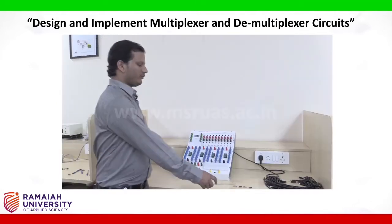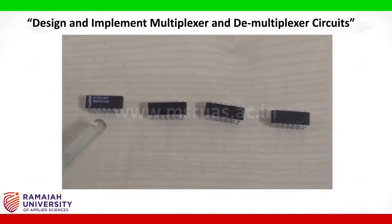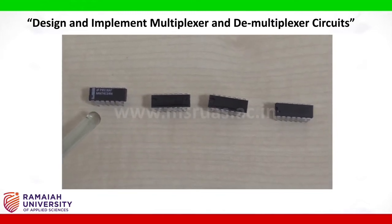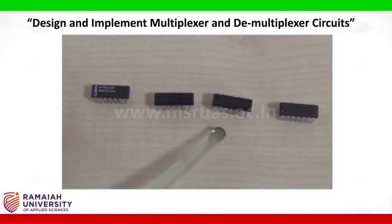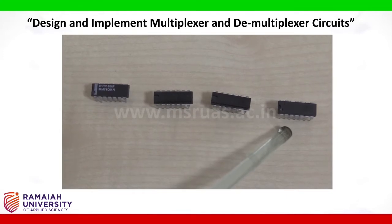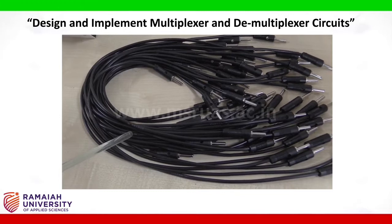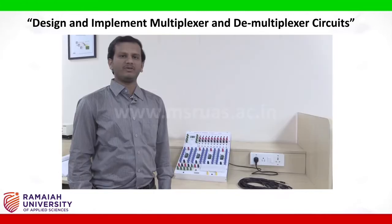These are the 4 ICs which we are using in this experiment. One is a NOT gate, these two are 3-input AND gates, and this is an OR gate. These are the patch cords we are using to connect the logic diagram. Before using any patch cord to connect the given logic diagram, we have to do the continuity test for each patch cord.